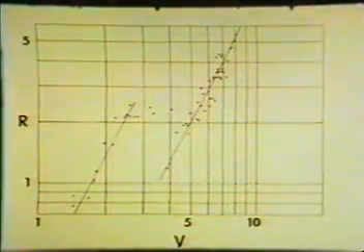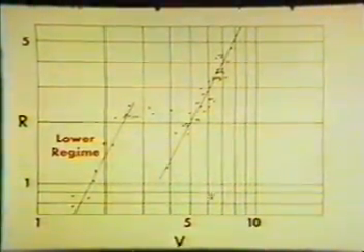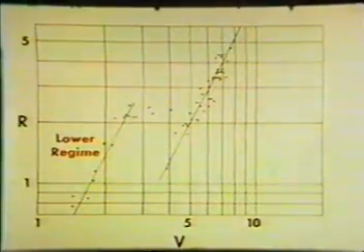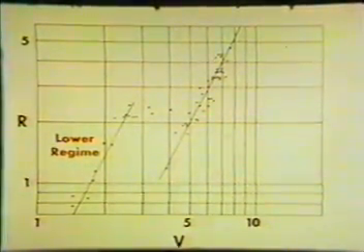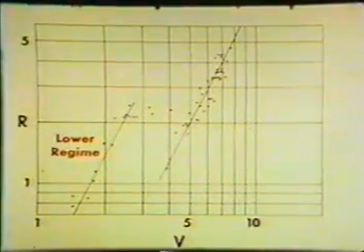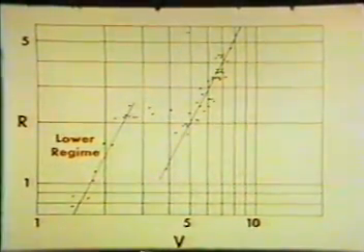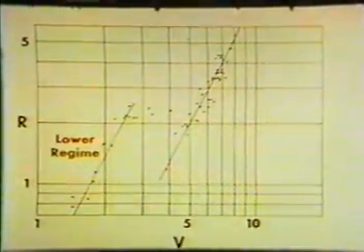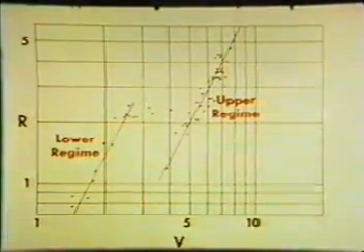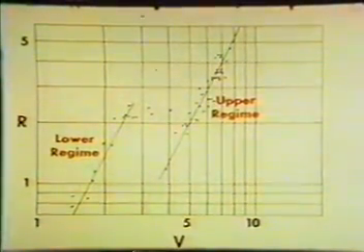The left-hand curve is the average depth discharge relation for the lower flow regime when the bed was dunes. The right-hand curve represents an average relation for upper regime flows when the bed form was plain bed, standing waves, or antidunes.